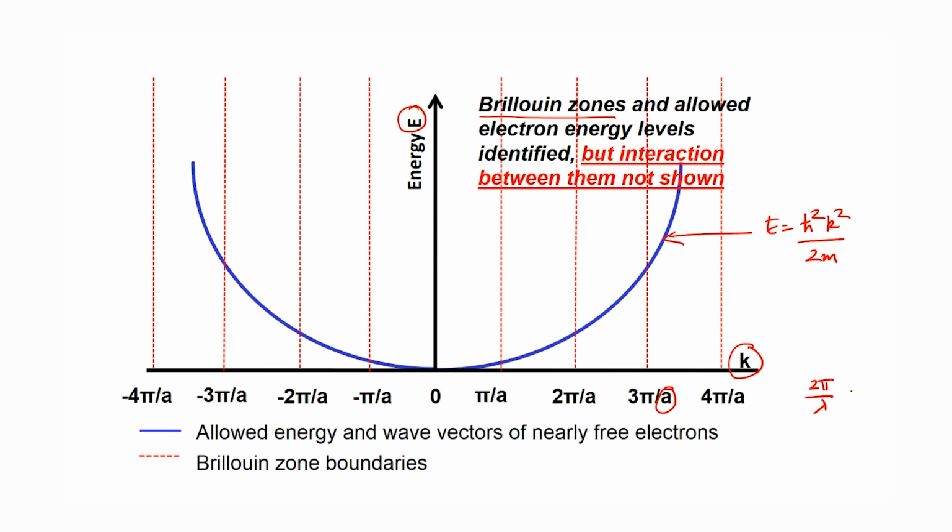This is called reciprocal space notation, not very critical for you to know the name, but the point is that what is plotted on your x axis at those specific values where I am plotting those dotted lines represents the periodic structure of the material, and you can see all the parameters here which indicate that. So, there is a periodic structure for the material which is represented by those dotted lines, and there is a free electron parabola which corresponds to the behavior of the electrons inside that material.